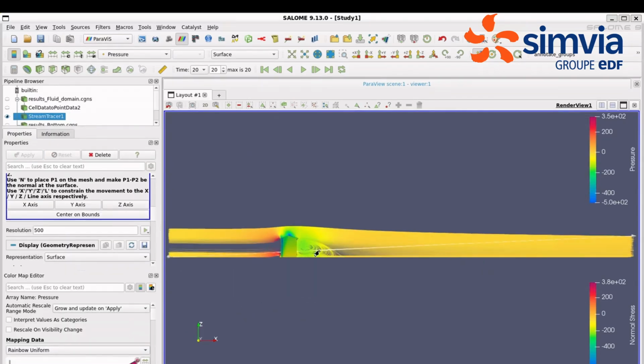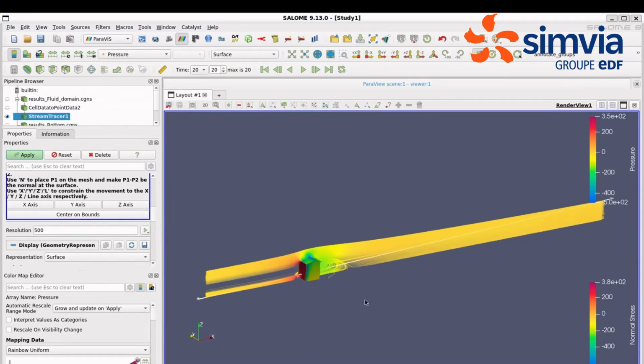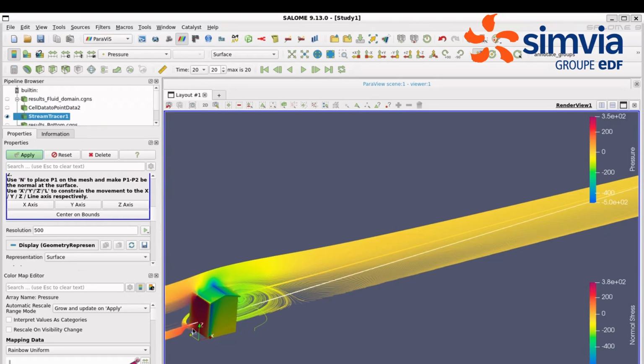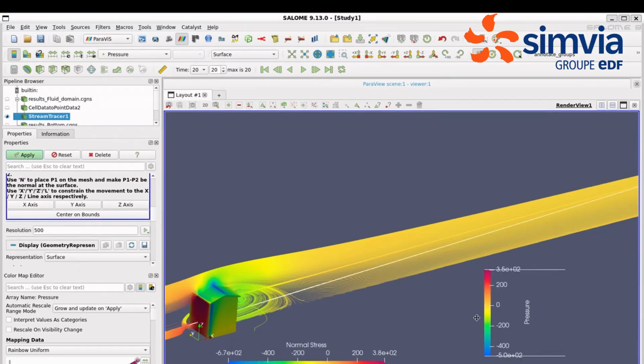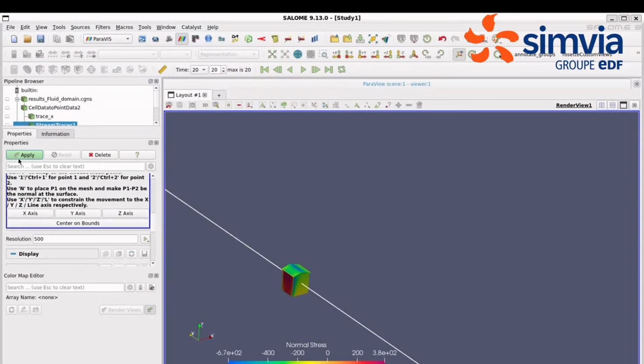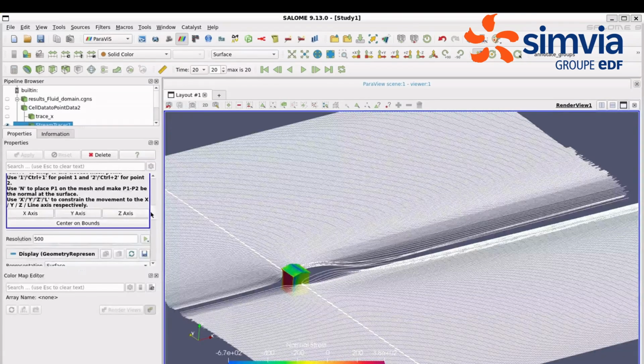Right behind the building, the characteristic eddies typical of turbulent flows are clearly visible. If we now focus our attention on the house, there is a red face corresponding to a maximum of the pressure color map. This makes physical sense, as the wind is along the plus X direction and is therefore applying a consequent pressure on that face.